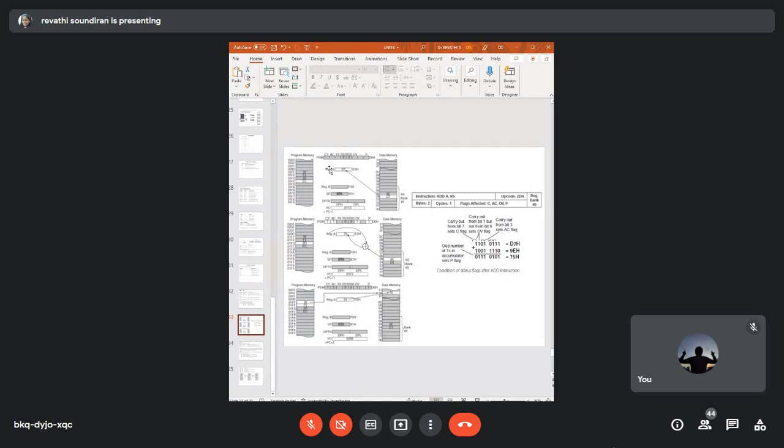Okay, so now let's understand that we have loaded the program in the microcontroller, in the memory location. So this is the program that we have loaded. This you have to understand with the help of your mnemonic opcode sheet, which has the related opcodes. Say for instance, your addition operation has the opcode 2D, so that is written here. The instruction related to your move instruction was EC. So relatively you write your program there.